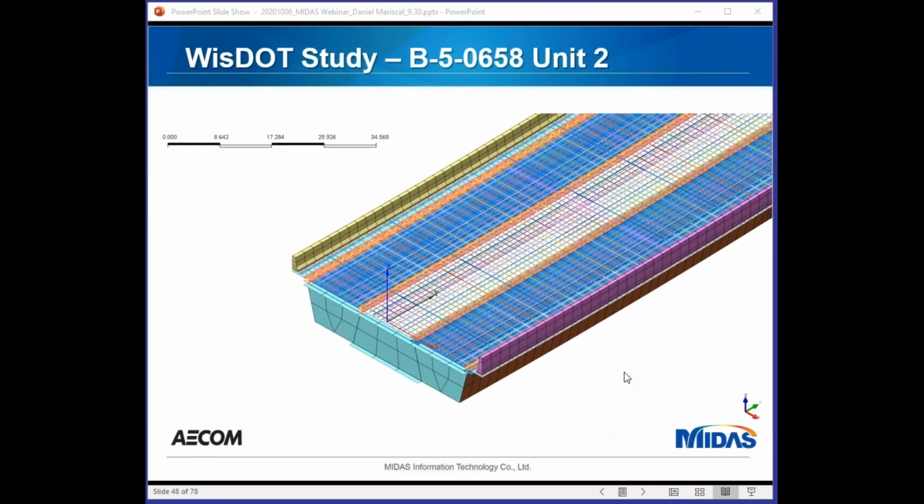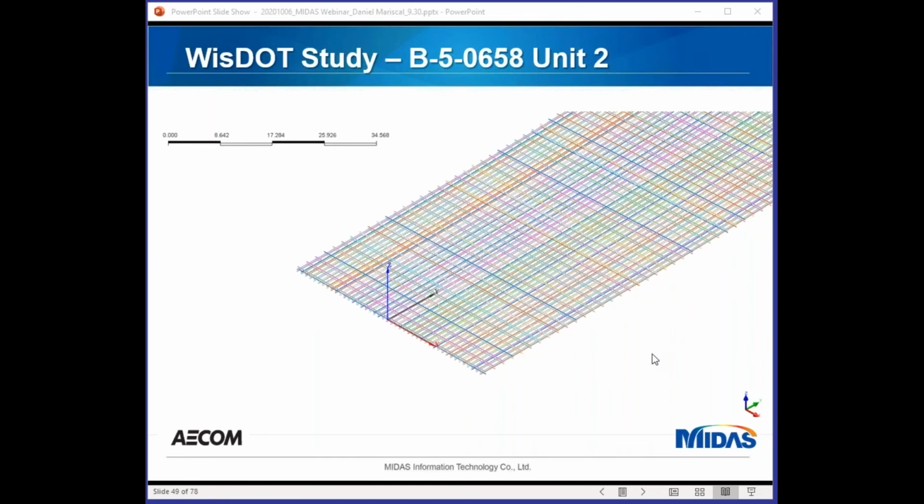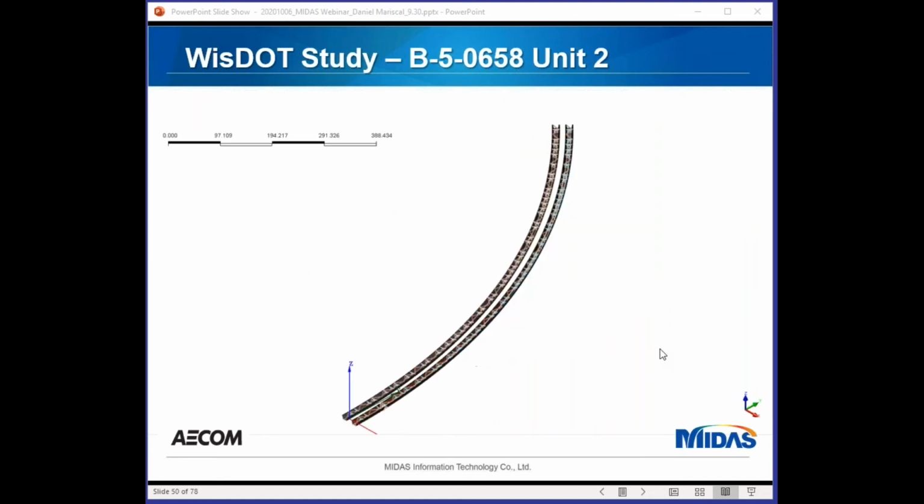This is the same view, but now you have the steel reinforcement elements. There's transverse reinforcement and there's longitudinal reinforcement, just as in the real bridge. This is a view of the reinforcement only. The reinforcements are embedded in the concrete, so when the concrete deforms, the rebar also deforms. They're joined together, and it's all joined by the program. You just tell it this reinforcement goes into this concrete, and then the program does all the background work.